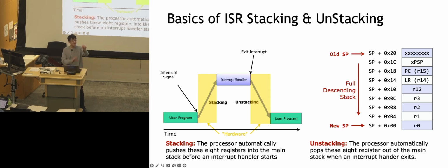Cool. Yes. Is it possible to pass values to the ISR? What do you mean by pass values? Arguments to the ISR? Yes, exactly. Whatever was saved in the register, you can put in as the argument, which is why we saved R0 to R3, so that you have the space to put in arguments.